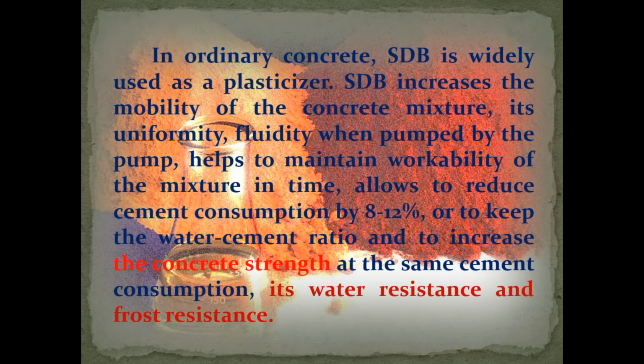It helps to maintain workability of the mixture over time, and allows reducing cement consumption by 8–12%, or, at the same cement consumption and water-cement ratio, increasing the concrete strength, water resistance and frost resistance.